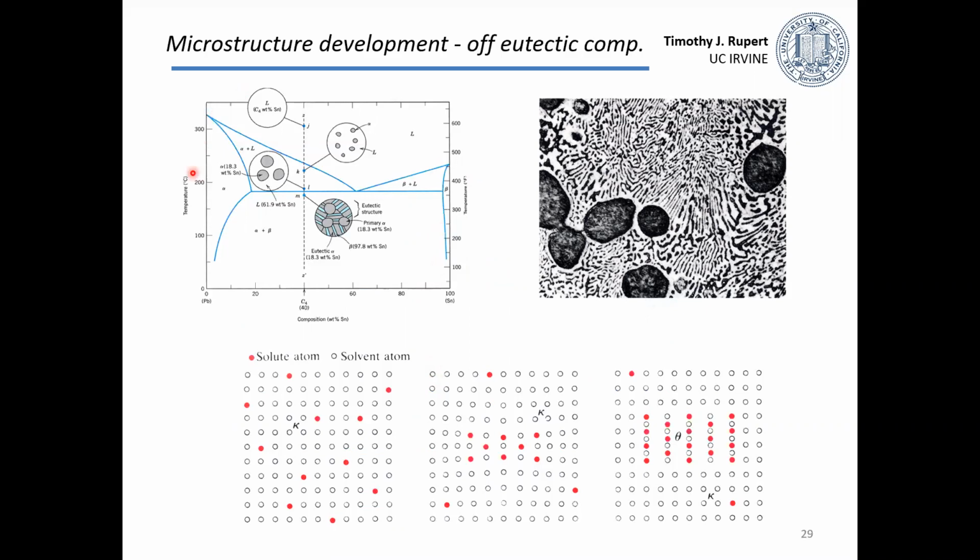We'll talk about ways of developing these types of microstructures. So don't worry too much about what's in this top left picture of this plot. But this is showing that if we add some solutes to our system, at the beginning, they'll just replace those atoms in a substitutional defect type of way. So here we have some of these red atoms just on the same original lattice.